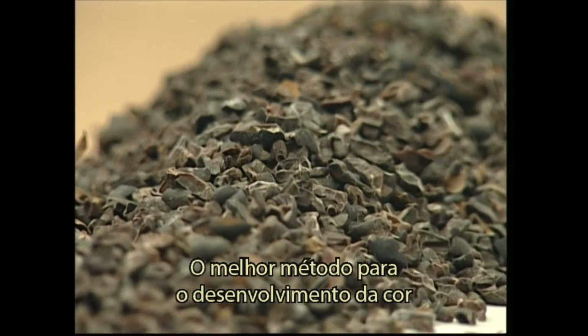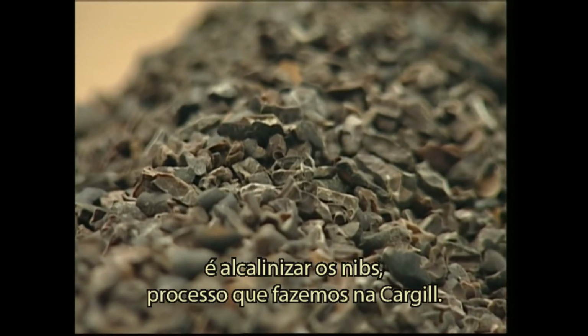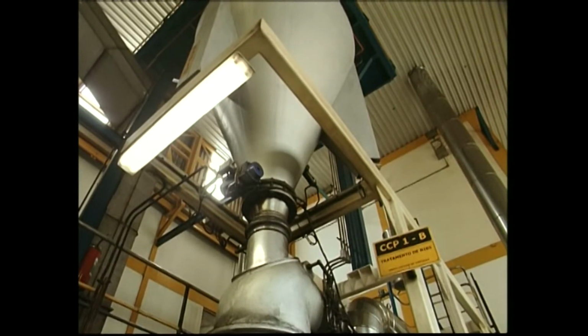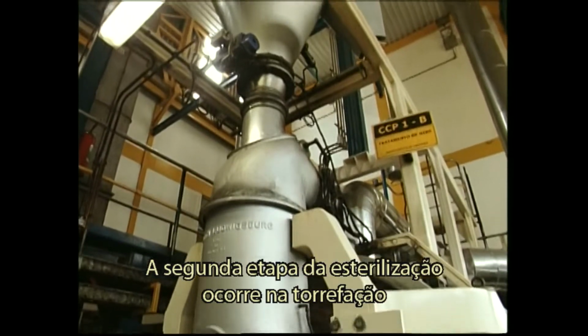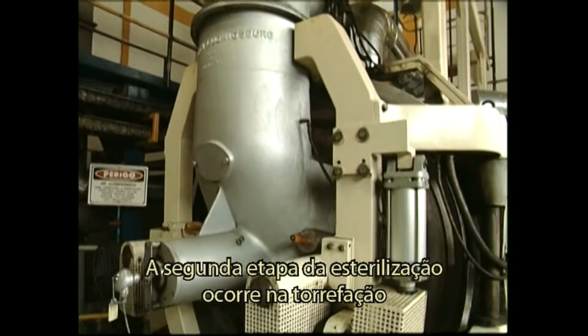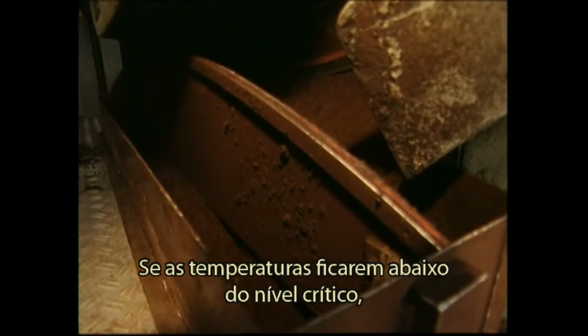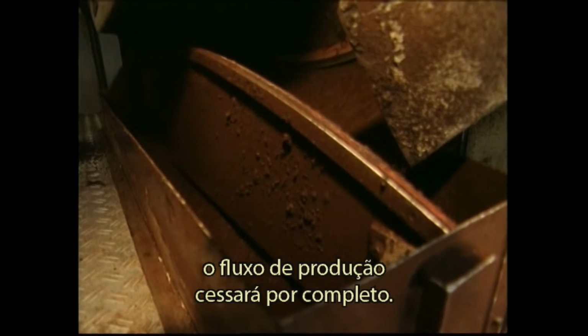The best method for color development is to alkalize nibs, which is what we do at Cargill. The first sterilization step takes place in this phase of the process. The second sterilization step takes place in the roasting phase, and it's a critical control point. If the temperature drops under the critical level, the production flow will be totally stopped.